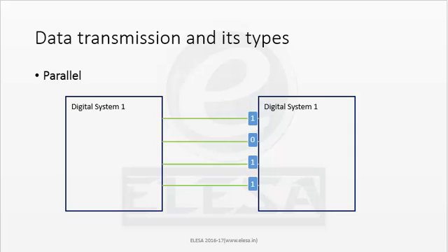Now that we saw both types of communication, we can conclude that serial communication requires more time than parallel communication to transmit an entire block of data. But with regards to hardware complexity, serial communication outperforms parallel communication, and this is particularly beneficial where the number of pins available on the hardware to transmit and receive data are limited.